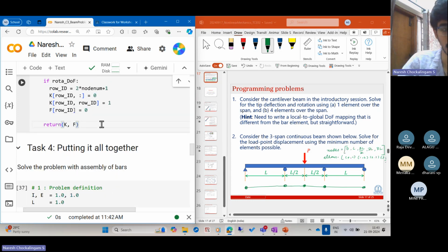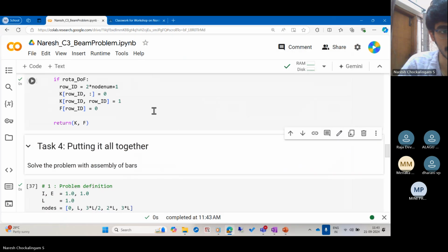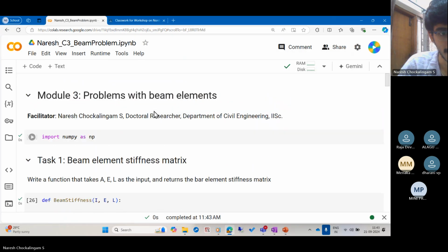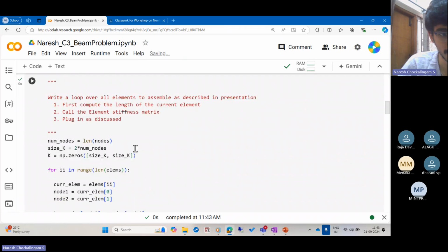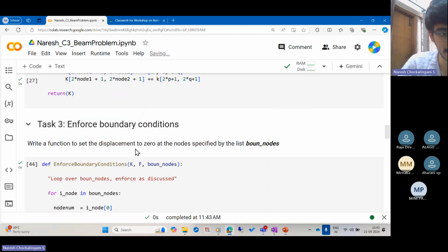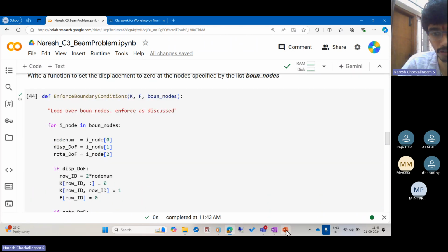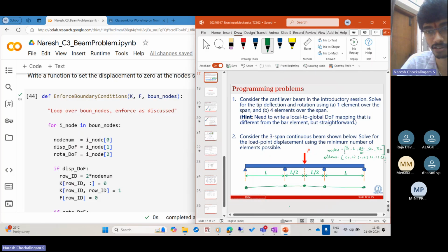Okay, we'll do one thing. I will share the code, and if there is any issue with the implementation, I will check it with the analytical solution, the structural analysis solution for this. So this can be solved as just a half problem. It's just indeterminate to 1 degree, right? You replace this with a guided roller and make this a redundant, and this can be solved with that.